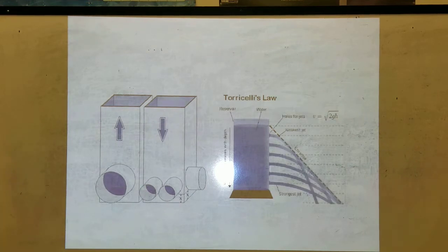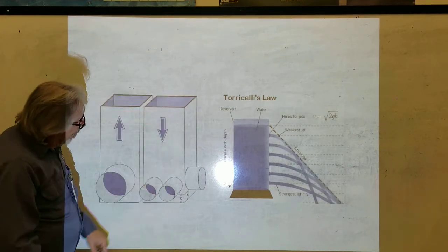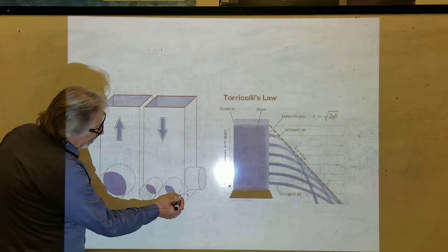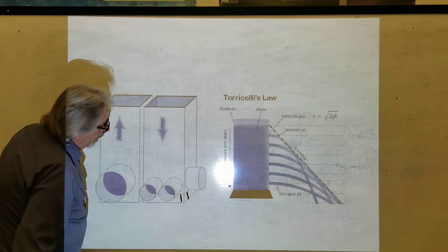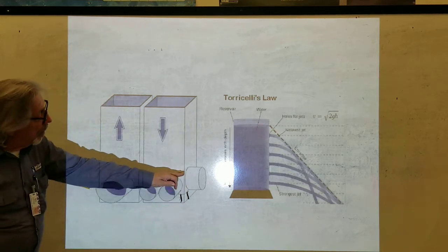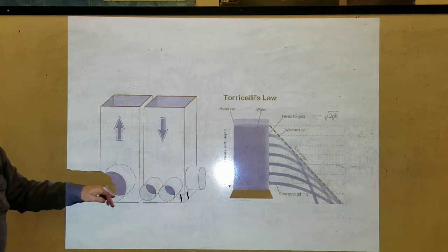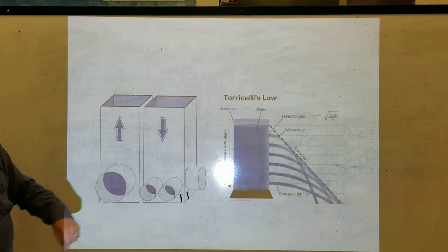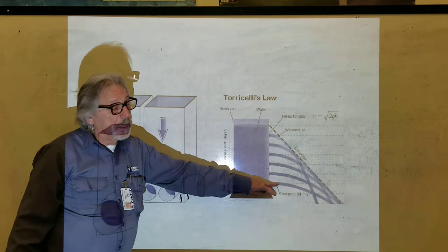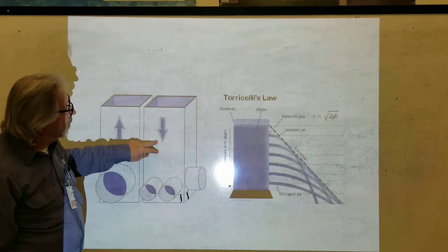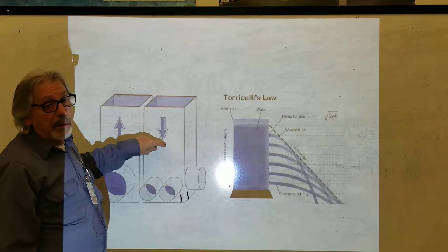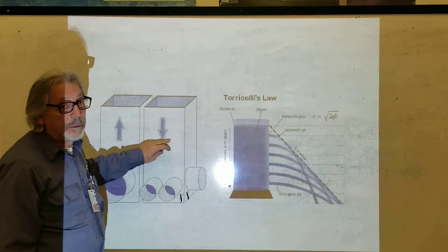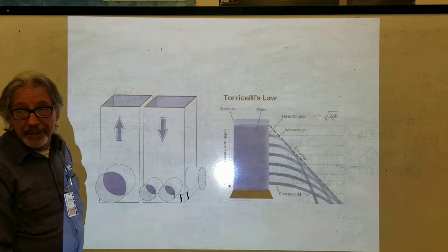That means that when you drop the air down in here, you want it to come off the bottom. So this dimension, right here, is gonna have to be the same on all runs, when you tap the collars in. Right, because this is what you want. You tap the collar in up here, guess what you're gonna have? Come on, what are you gonna have? Weakest jet. The weakest jet.